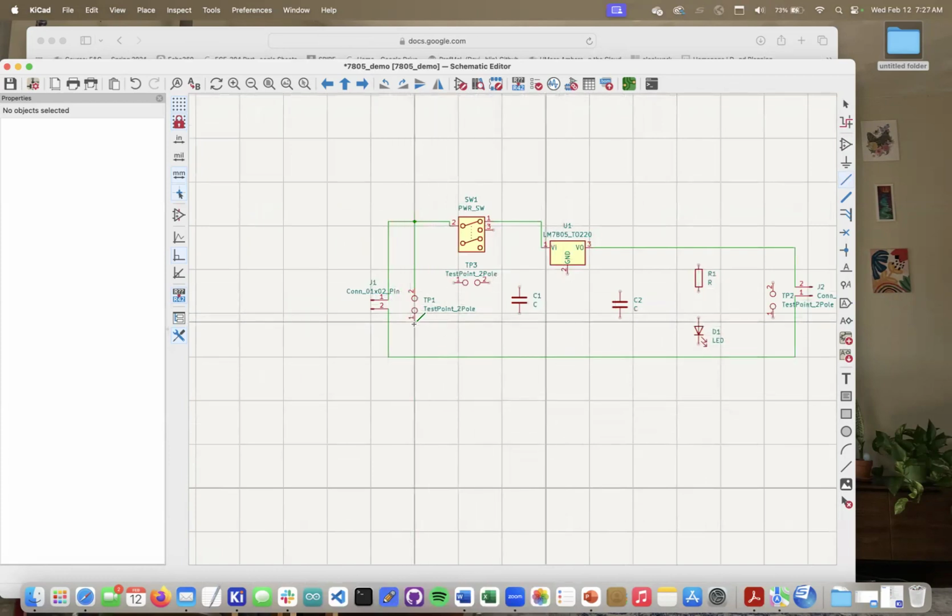Let's see, I have to connect this test point here. All right. Okay, something that's a little tricky was the switch. Now recall that in one position, we're just connecting the input over to the input of the, well, that is our voltage input, we're connecting to the input of our 7805. In the other position, we're using that as our way to measure current. So I'm just going to connect that down here to this test point, and then bring that back up.